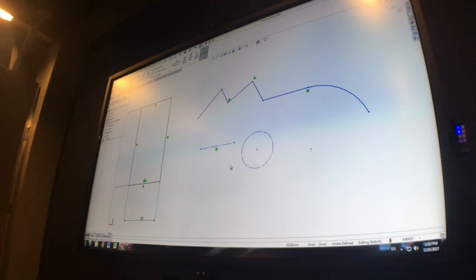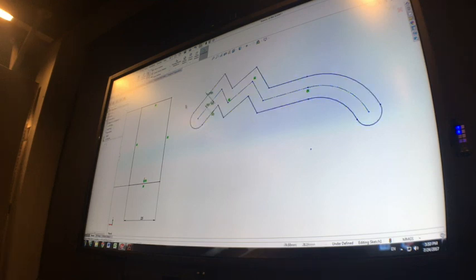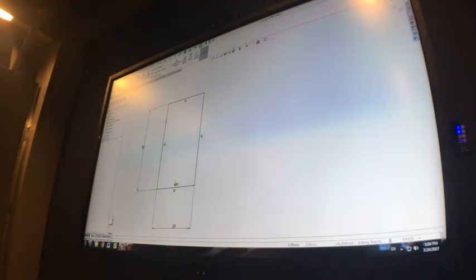included there. So if we have this shape, and we do a cap ends and construction geometry, change the base to construction, it means we've now got this nice enclosed shape that we can easily extrude. Right? So that's the basics of the offset. So we're going to offset this shape.